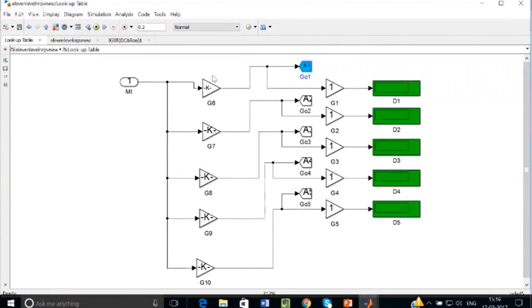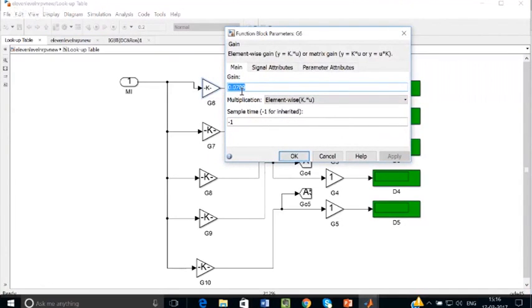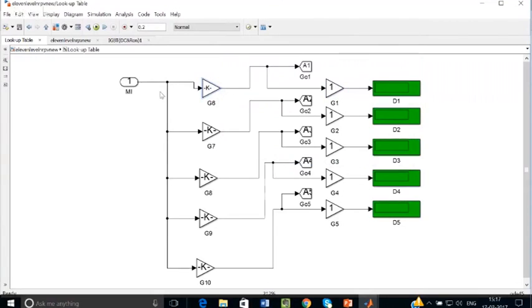So what we have to do, say this is for Newton-Raphson, I have given the angle. When I find for GA, come here and give it for GA. GA will also give you some angles, 5 angles. You come and give the GA angle here. When you find it with PSO, come and give the PSO angle here. Okay, when you want to do it online, in this case only one, I am measuring the modulation index. For when that particular modulation index comes, I am giving the gain here. This value is fixed. You can remove this. What you can do is you can put a neural network in this position.